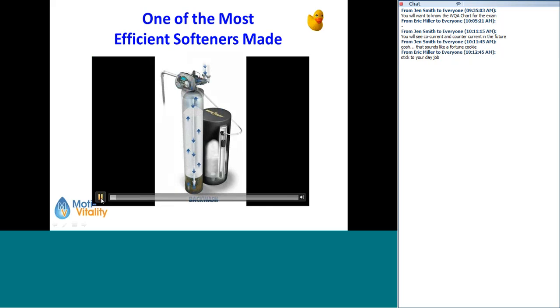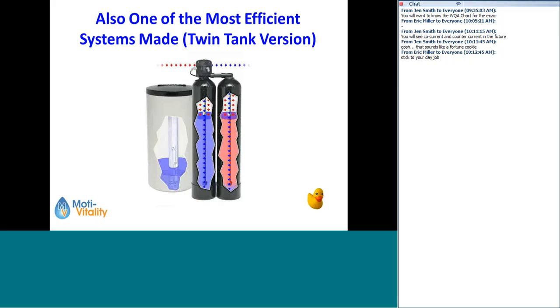Now this is the backwash from the regeneration cycle. You'll notice water's flowing down through the distributor tube and up through the resin. See how it's lifting that bed up and taking up area in that freeboard area, but it's hitting the bottom of that resin bed first.